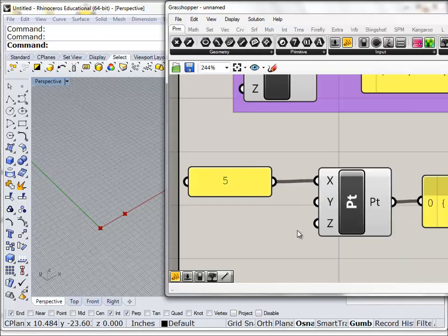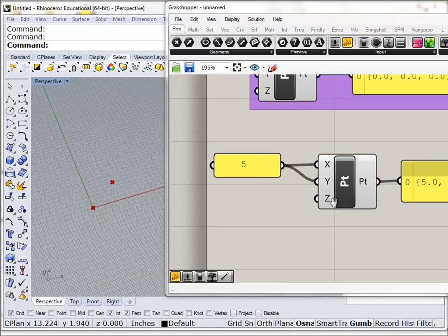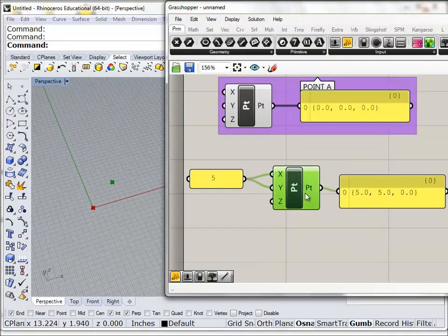But we're going to do these connections and disconnections all the time. So if we want to do this faster, if you hold down Control, you would see that there's this minus sign that's appearing, right? And that would allow you to disconnect your components. And this disconnection could be from either direction. I could disconnect from one end or the other end. It doesn't matter. I could use the same input to input into two variables. So right now, my X and my Y are 5.